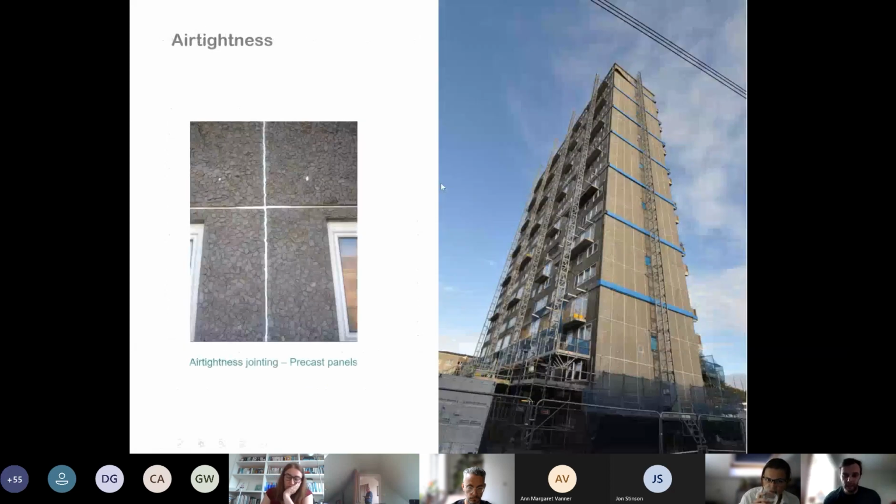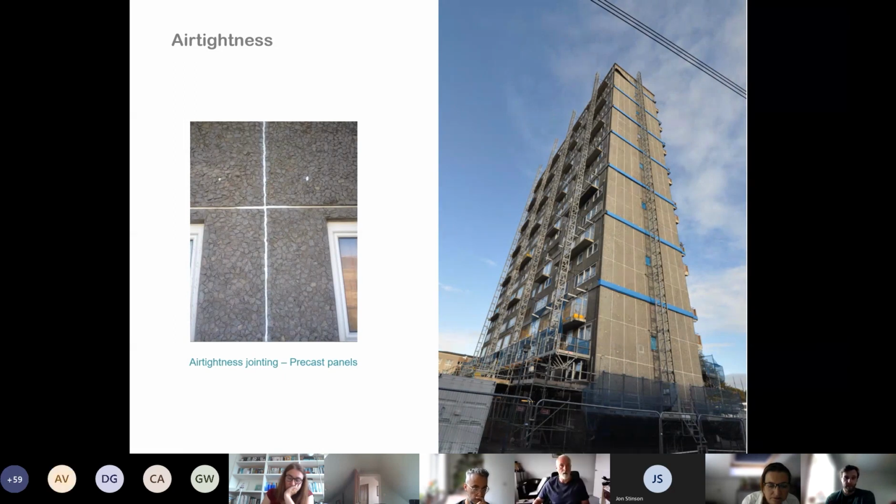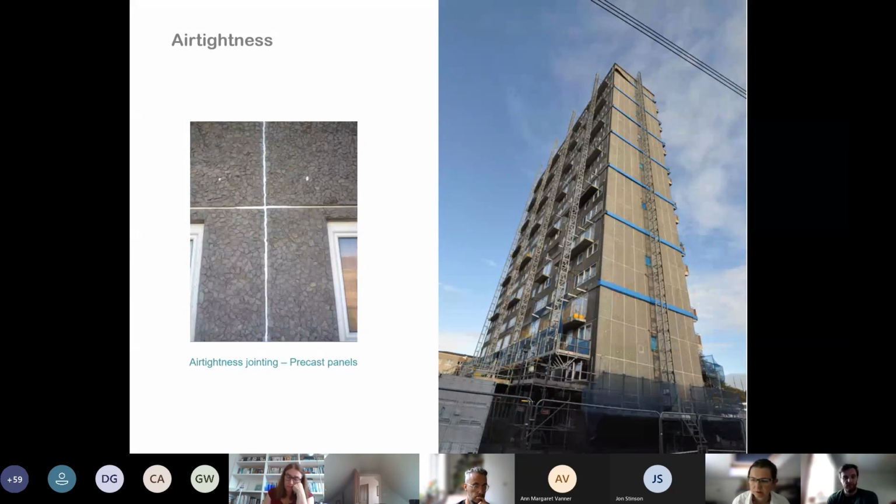And the methodology that we use for that, just taking a slightly more pragmatic approach, is to utilize the inherent air tightness of precast concrete and seal up the joints in the actual concrete panels with a foam backer cord and a flexible mastic to seal the joint. We did quite a lot of research into the performance of the mastic to be used there. There's also, and this is quite a large heat loss area, these small white dots of mastic, which were actual drainage slots in the precast panels. So wind was previously blowing straight into the apartments, and the only thing going from there into the apartment was a layer of plasterboard. That's why everyone complained of drafts previously.